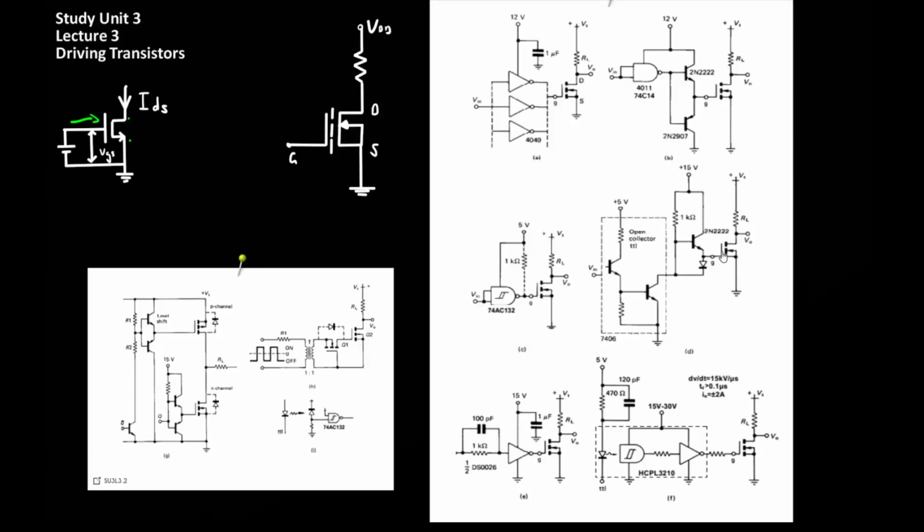In all these examples, the voltage or the clamping voltage at the gate is either 0 and 15 volts, or 0 and 12 volts, or sometimes 0 and 5 volts. And this is a problem because very often, for noise immunity purposes, the switching voltages may vary between plus and minus 15. In other words, the switching signal might vary from plus 15 volts to minus 15 volts, passing through 0. Because the controlling signal might vary between a negative and a positive voltage for noise immunity purposes, it may sometimes be required to have a driving circuit which can accommodate a negative switching voltage.